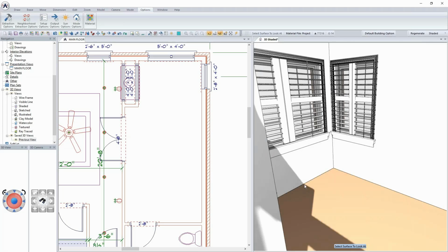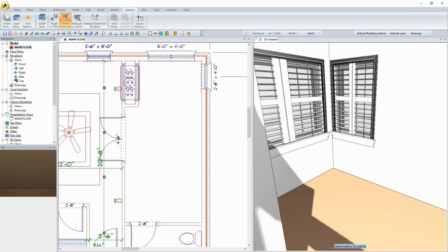And I will be jumping back and forth between different modes, whether I'm looking at 3D shaded versus the floor plan, because I really do feel like having the 3D model open is going to help you for space planning. It helps me with the design perspective, etc. And then I jump to the floor plan when it comes time to actually dial in on getting exact dimensions and so on. So as I'm clicking on the main floor plan, and I come in through the draw option